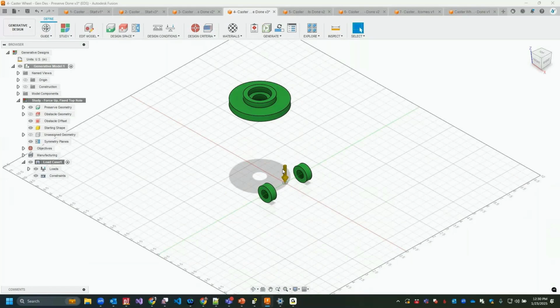Right now you can see there's a load on here. That's actually a gravity load. It automatically comes in. Of course, gravity is going to apply to everything, so I'll keep that on. But if you wanted to use this on Mars or some other location, you can actually change those magnitudes and everything in here, and change those units.